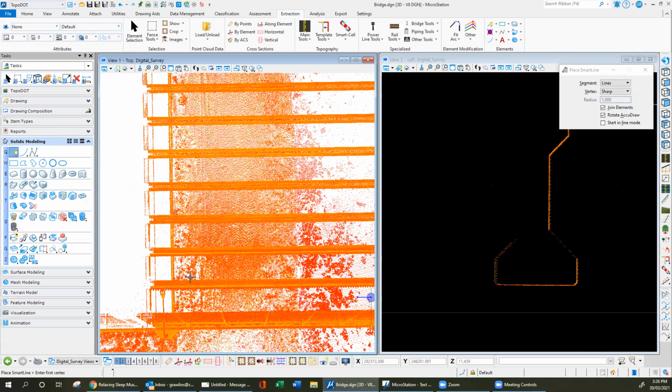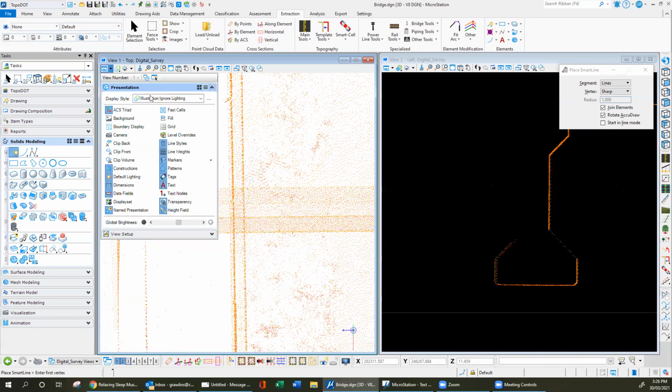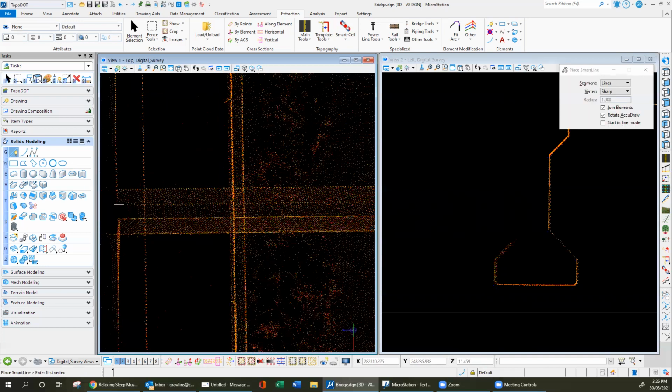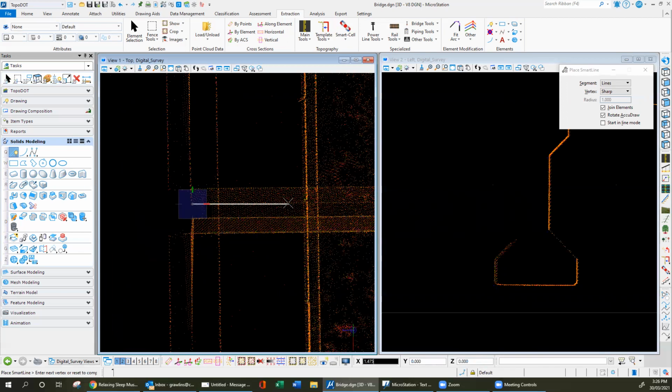And I'm not going to choose one of these. I'm going to go over the fourth one, 1, 2, 3, 4, and I'm going to place it. You could go straight down the middle, but you're not going to get it perfectly accurate. We want to find a better way of lining that up if we can. So in this particular case, I'm going to trace over exactly that particular web member, and that'll get my XY alignment going as accurate as I can.